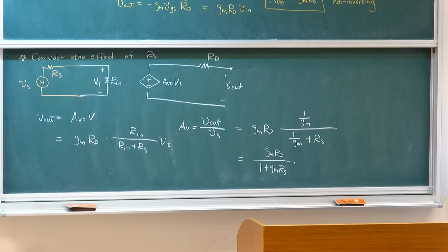So anytime you have source resistance, it's a voltage dividing effect. It's the same voltage dividing effect, whether it's dividing under or dividing from here. This is ground, and your voltage is being divided between VGS and RS. If your signal comes from the bottom or from the top, you get similar results.